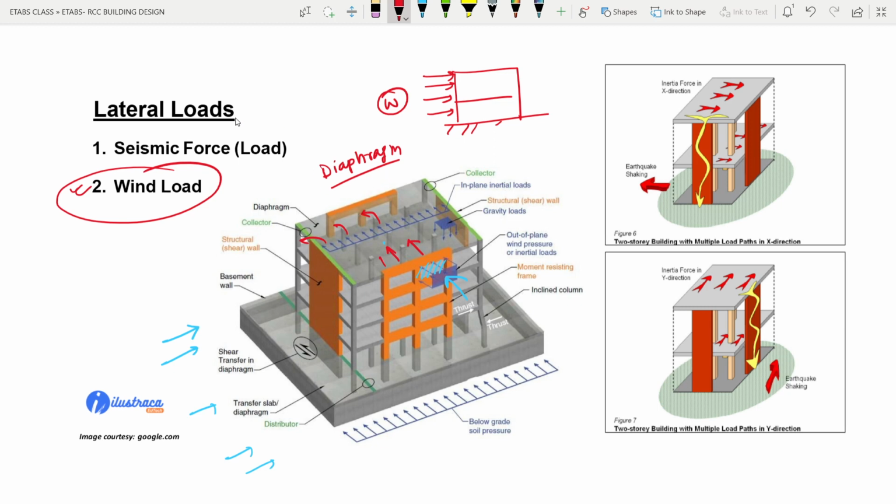Okay. Now the same in the case of seismic force. Actually, seismic force or seismic load is not a direct force like our wind load, because seismic activity is just ground shaking. The ground shakes, right? Now when we have to-and-fro motion in the ground, what do we get? In building design, we find out the base shear, or the base reaction that we get at the base level, and then we distribute this force like this.